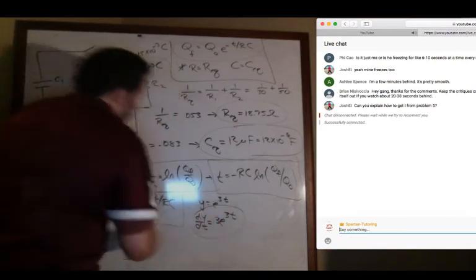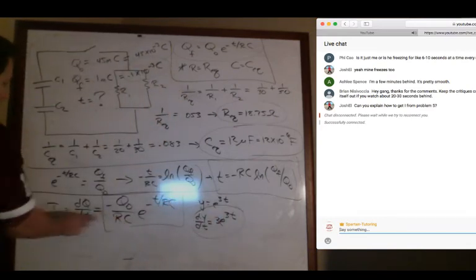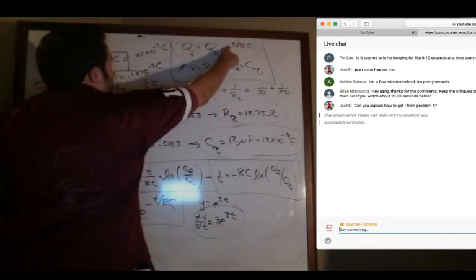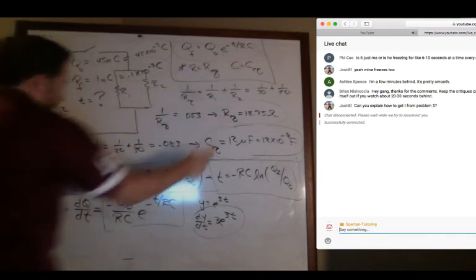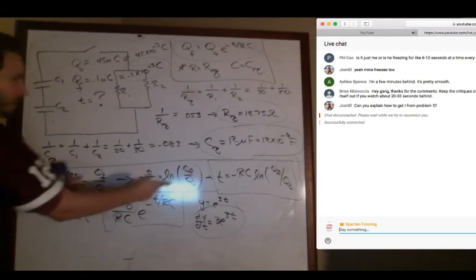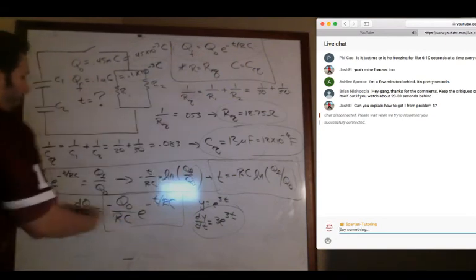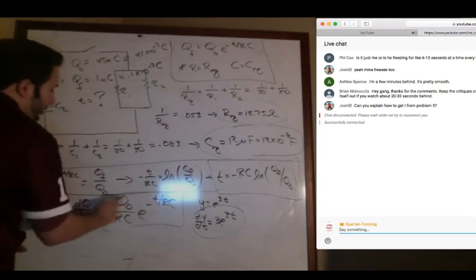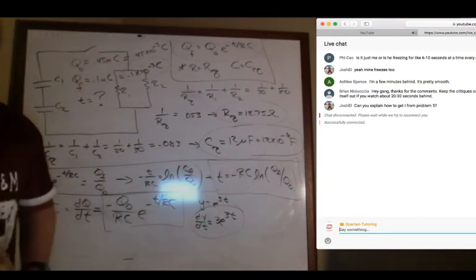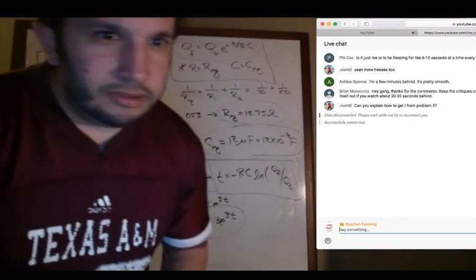And that would be your derivative. And so all that I'm doing here to find my current is taking the derivative of my charge. The number in front of that t, think of it as negative 1 over RC. And so I take that negative 1 over RC and multiply it in front. That's the derivative of that function. And then we've already got RC, Q naught, and the t we would have found earlier in part A. So hopefully that answered that question.